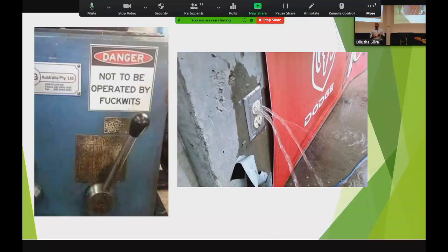That could be another way of circumventing your interlocking system, because if you're one of those, don't come in the room. And the one on the right, again, that's in the States, but that happens. Water gets into the system. We had an incident not too long ago where someone was drilling a hole in the concrete slab, and when they core drill, the core drill uses a watery slurry to not burn the blade out. He'd done all the survey work. As he went through, he picked up a pocket which had a plastic conduit in it. Water goes in the conduit, tracked a good 10 or 15 metres along, then drops straight into a switchboard. So that does happen. All right?